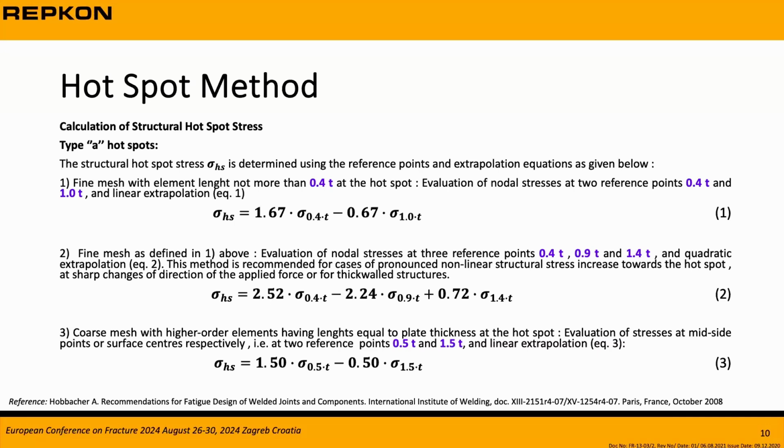Fine mesh as defined in here, evaluation of nodal stress at three reference points, 0.4 T, 0.9 T, and 1.4 T, and quadratic extrapolation given below here. This is the second one.